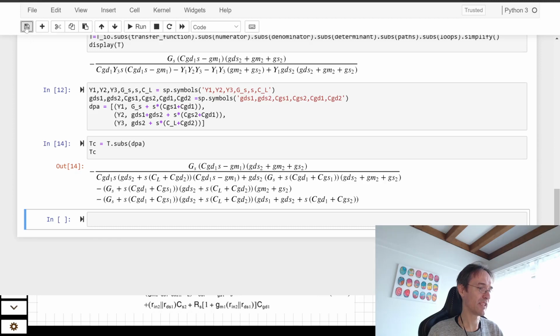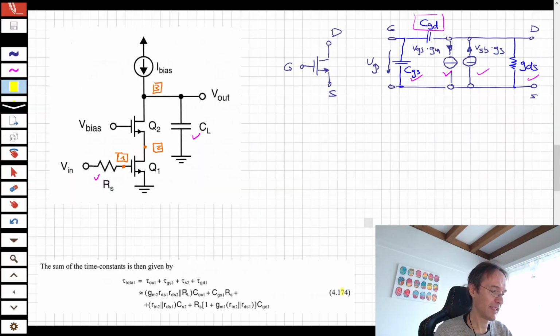In this textbook here, the one I took it from, they say there are shortcuts to derive a few of the time constants. Then if you have all of those time constants, you can more or less add them, and then you get the speed of the circuit more or less. This is the zero value time constant principle. I always forget the order of the name, yes. But it actually would work. However, they have 4 time constants here.